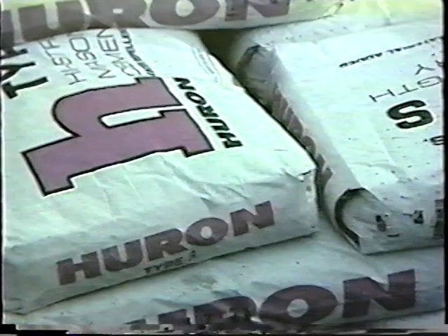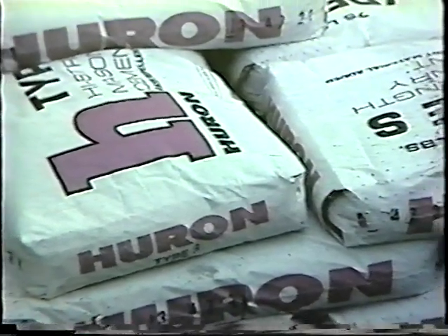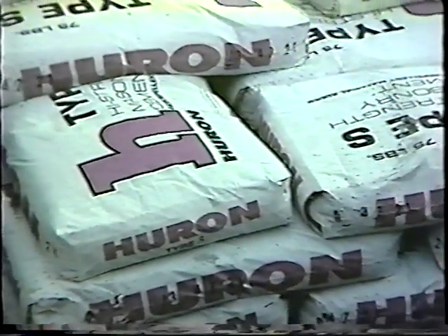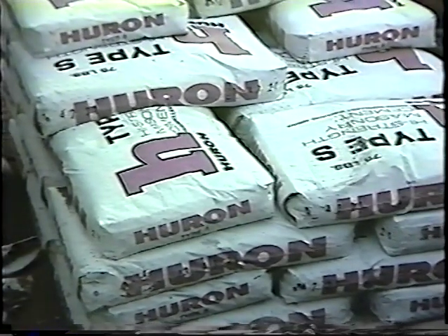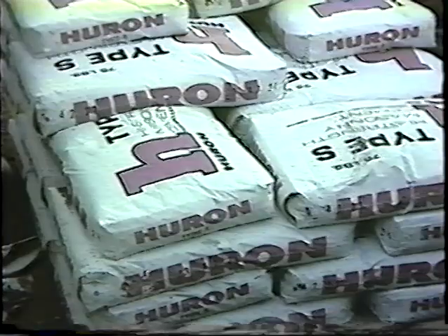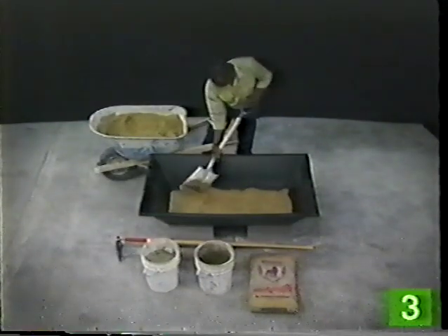Masonry cements are combined with sand, or combined with Portland cement and sand, to make mortar. Types N and S masonry cements are used in mortar. Sand is most of the volume in mortar and makes it economical. Mason sand should be used, and it should be free of contaminants such as salts, clays, or other debris.